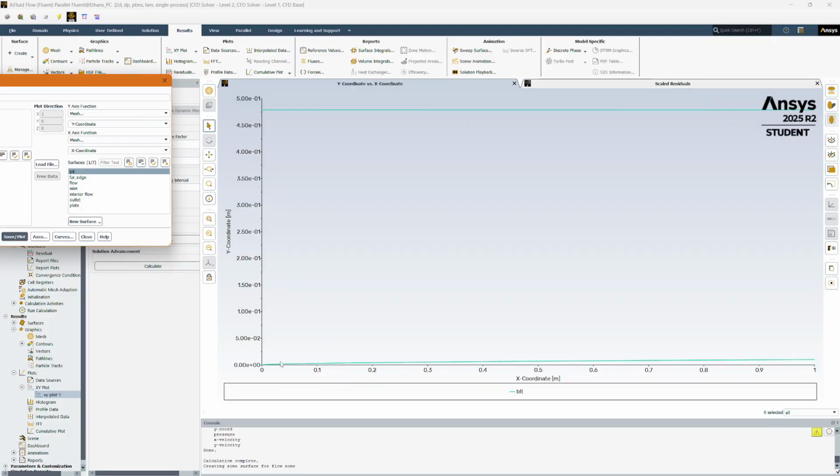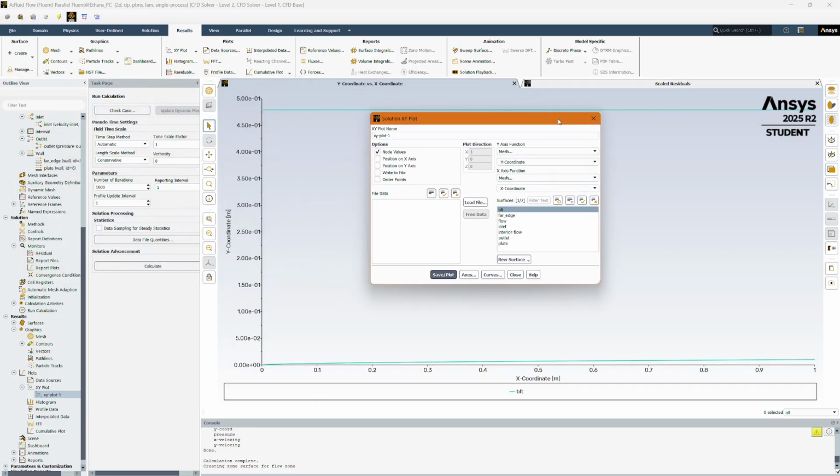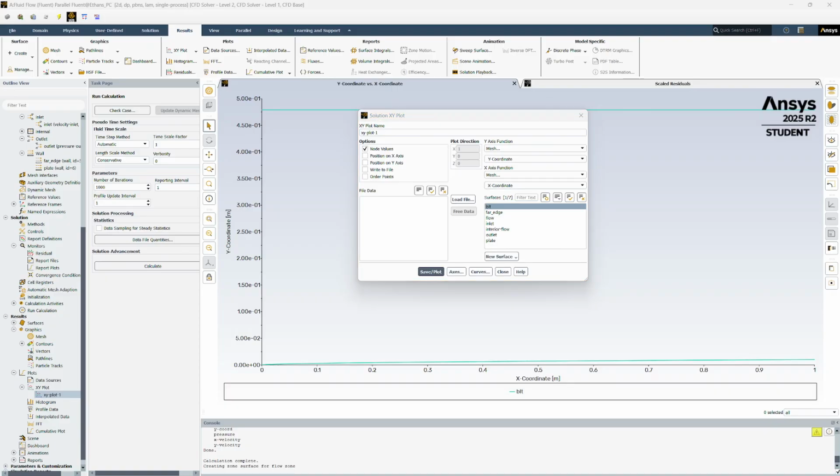There we go. So that's showing the boundary layer thickness throughout the entire thing. At the very edge, that's a very small 0.009 meters thick. So about what we expected, but you can see as it grows, starting near 0 and then growing all the way up to 0.009. All right. So that's the boundary layer thickness.